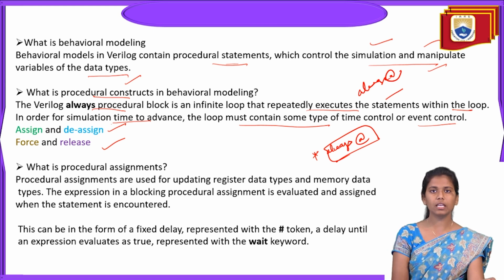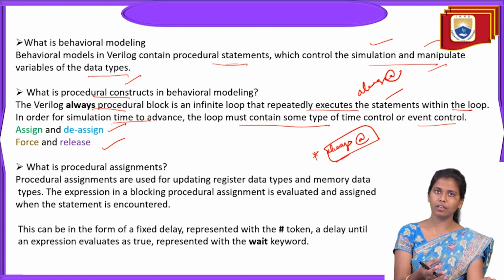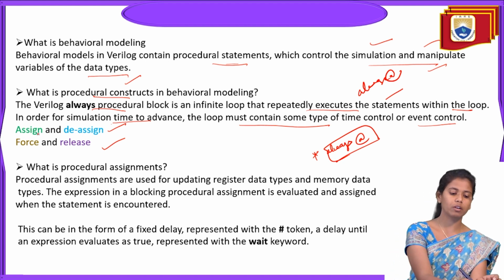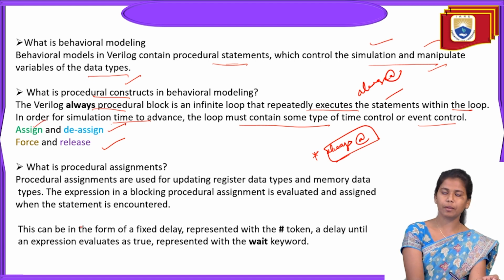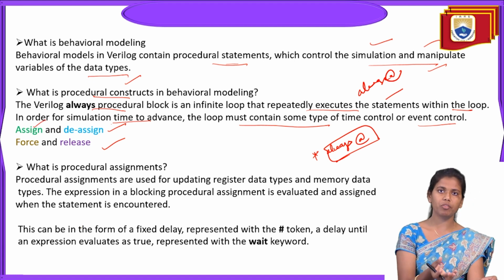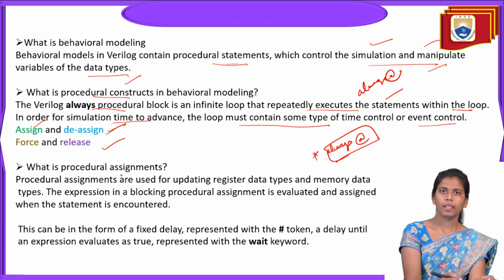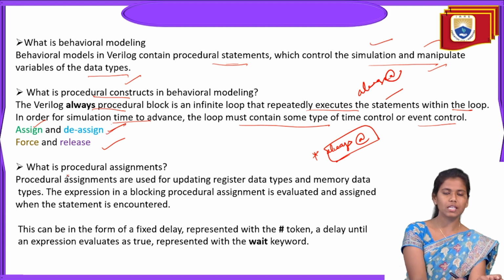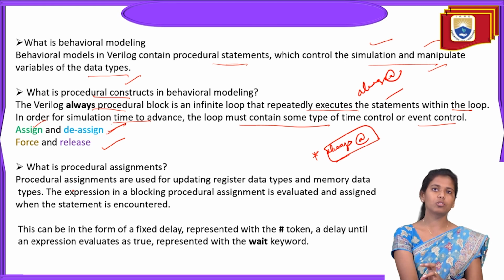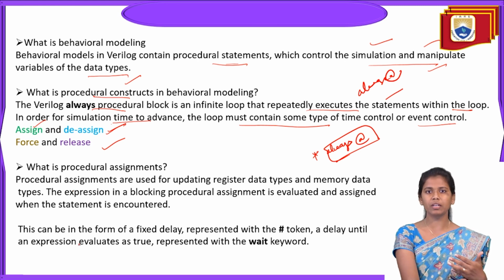If you are considering the construct assign and deassign, if you are adding some values to these data types, we need the keyword assign. And if you are omitting some values out of the data types, then you have to use the keyword deassign. Similarly, force and release are also similar to assign and deassign.